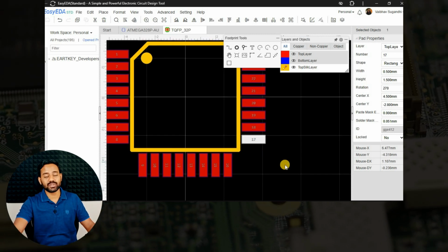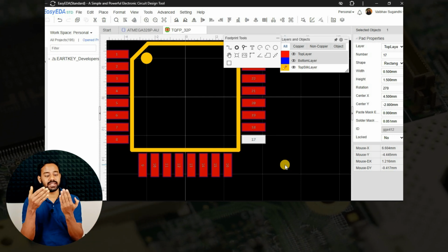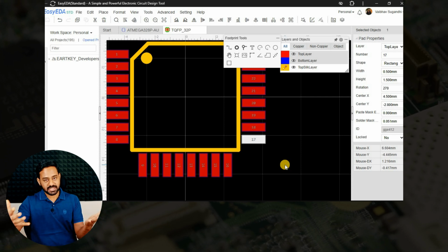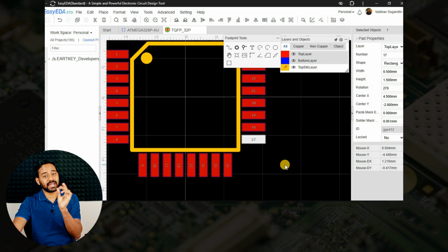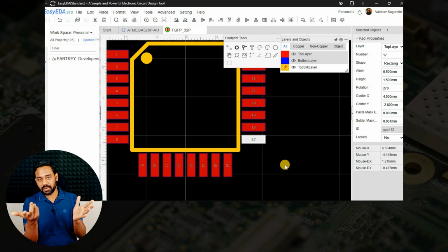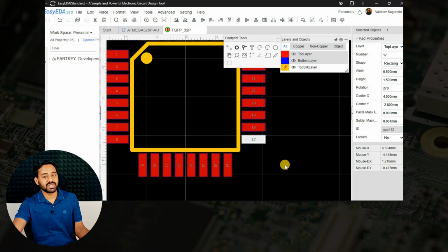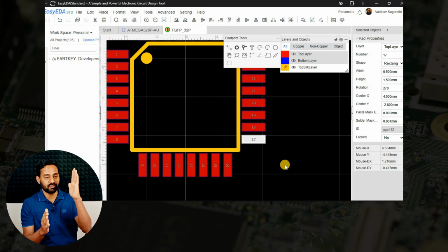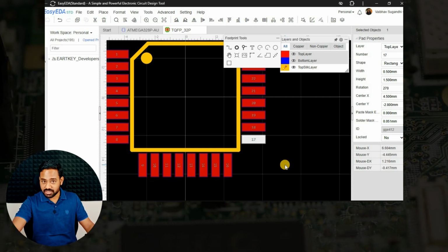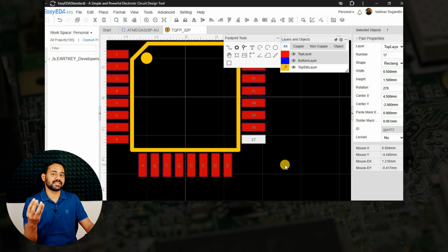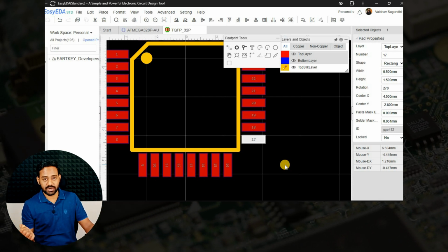But when we kept it 2.5 mm, the one pad of one side of the IC is getting overlapped with another pad, which is a problem. For that reason, what we did is we reduced the length of the pad or width of the pad, you can say, keeping the dimensions same. We have never changed the Cartesian geometry from one pad to another pad or the pitch for that matter, because we cannot change that. Our IC is getting manufactured with that dimension and we have to follow it no matter what is the reason.